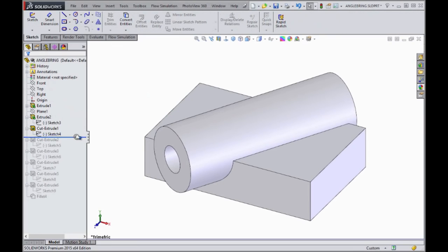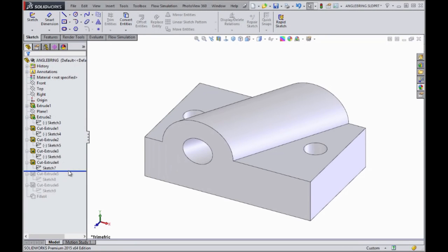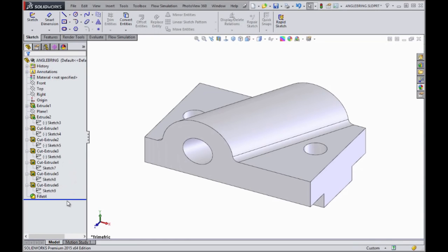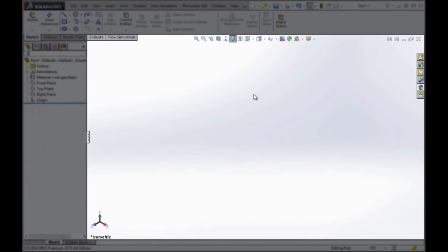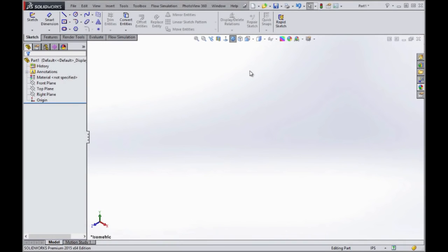As I said earlier, SolidWorks parts consist of various 3D features building upon one another to make a 3D part. These can be either applied features, which are applied to existing solid geometry, or sketched features, which utilize sketch geometry to define their profile, direction, and size. The graphics area is where you'll create and view sketch geometry.